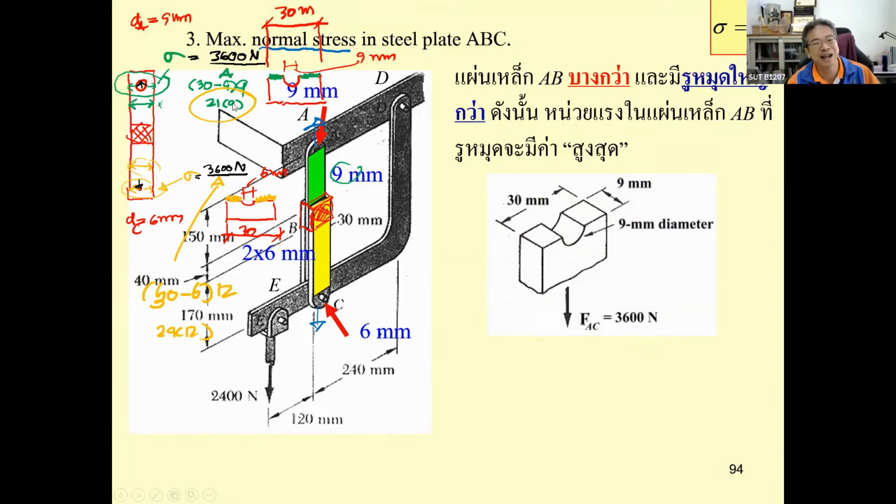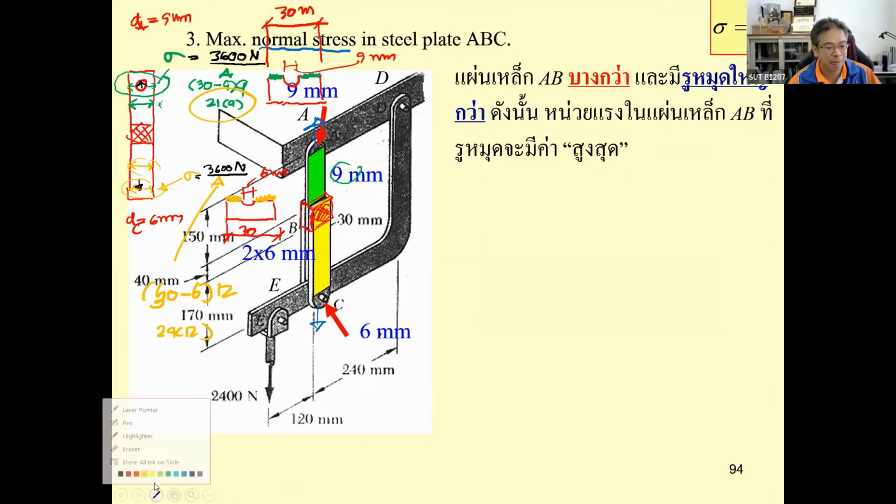And then you just compare the stress. It's going to be 3,600 Newton divided by 21 times 9 square millimeter. That is going to be megapascal.